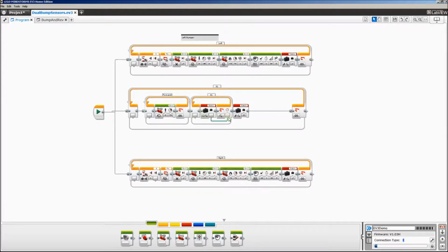This is going to wait for all these to execute: stop the robot, move it backwards, cause it to turn, beep, and then set the ready variable to true, which will allow the program to move on, which will then reset ready to false, and then begin the forward loop again. So that's just a bit of an idea how you'd run an interrupt in parallel.